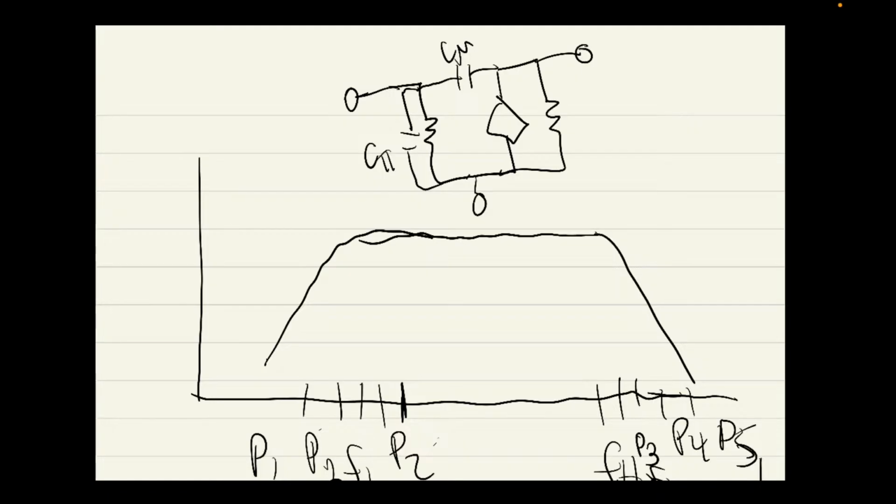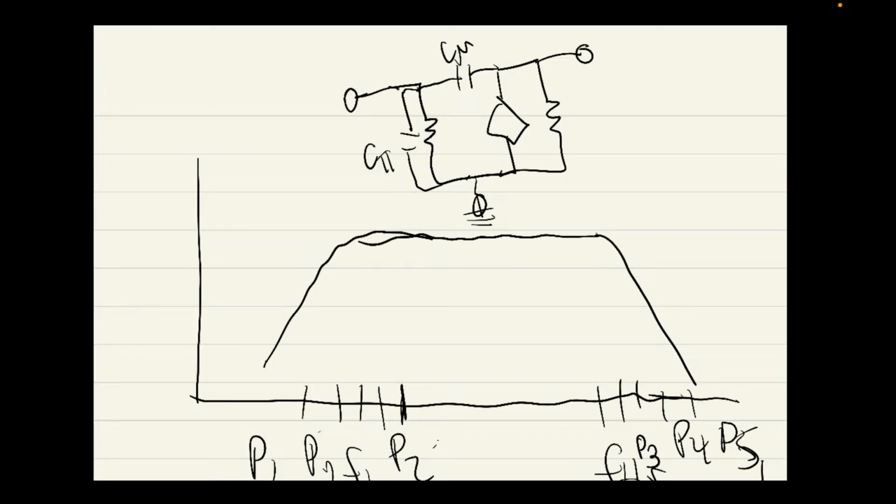So when we're doing our open circuit time constants, C pi might be easy to analyze because this is with respect to, well, commonly ground. I'm taking a special case here, but usually it's commonly ground. C mu is not easy to analyze because it's between two different nodes. It would be much easier if we could break this down into a different network that connects that capacitor to ground. And so that's what Miller's theorem is for.